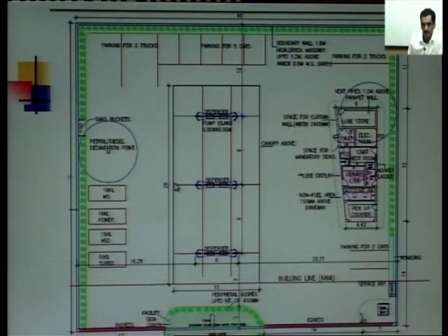So in most cases in urban outlets or in highway outlets where the space is lesser, we are going to have the tanks in brick masonry pit and an RCC slab over the top, and eventually the vehicles move over these underground tanks. But in case the outlet is situated in a remote area or where the consumption of petrol or diesel is a little lesser, in rural areas where the amenities are less, or in other words, where the company is not permitting, the owner is having a lesser budget, we are going to have these underground tanks in earth pit.